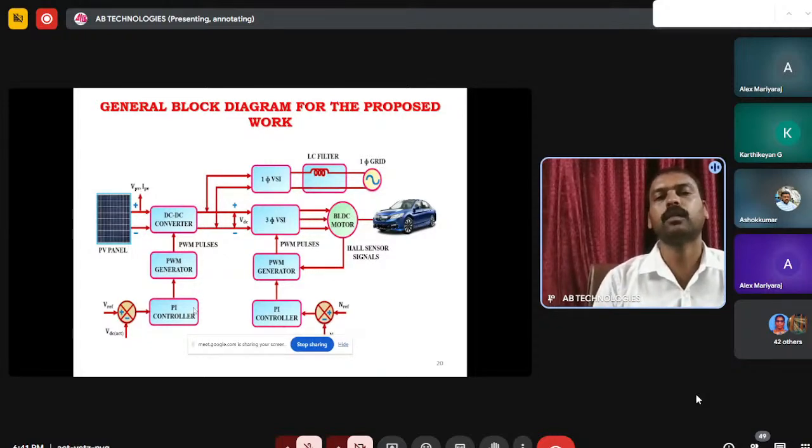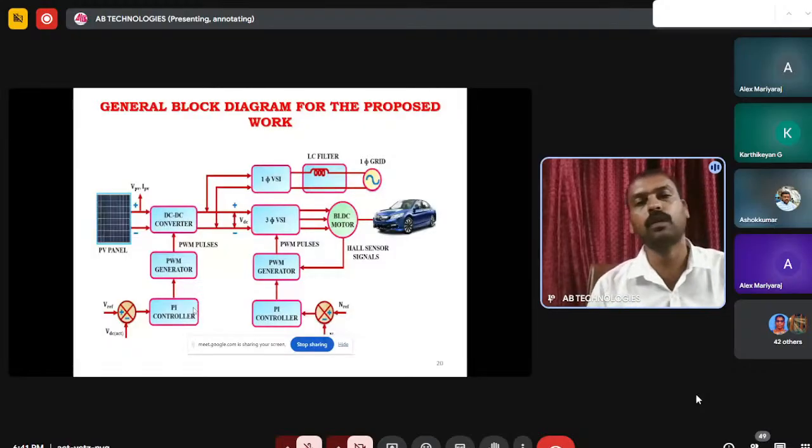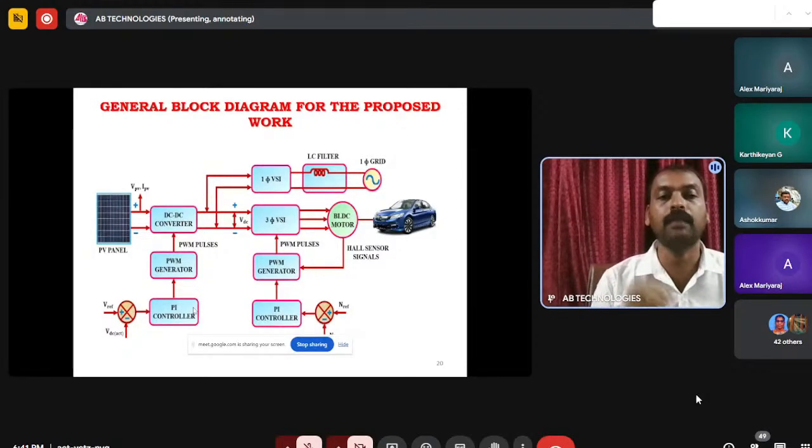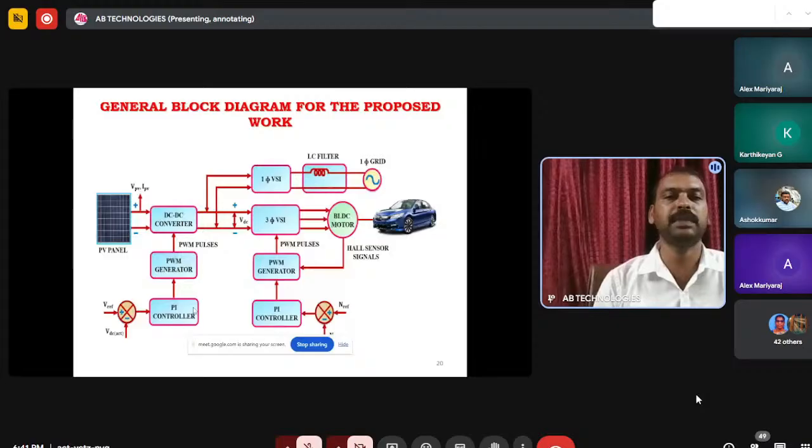Why? Because in a closed loop controller, you have to assign the reference voltage, that is, how much DC voltage you have to maintain. That reference voltage and the actual voltage from the converter are compared and the error is given to the conventional PI controller, proportional plus integral controller. That output is given to the PWM generator. In the PWM generator, again the carrier signal and reference signal we have to compare. That error is the duty cycle, and we can go to the DC to DC converter.